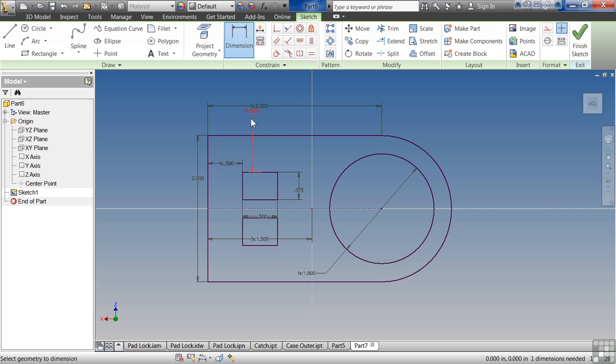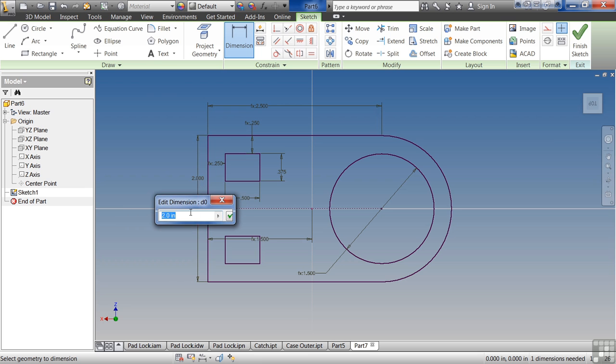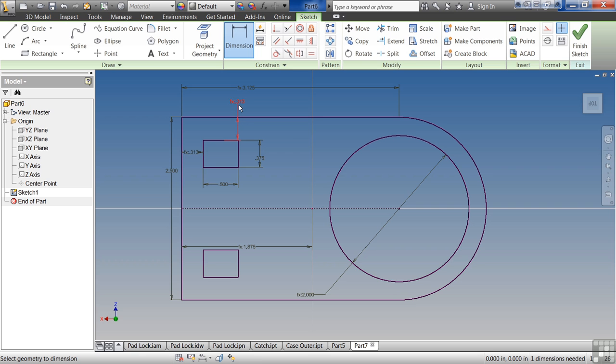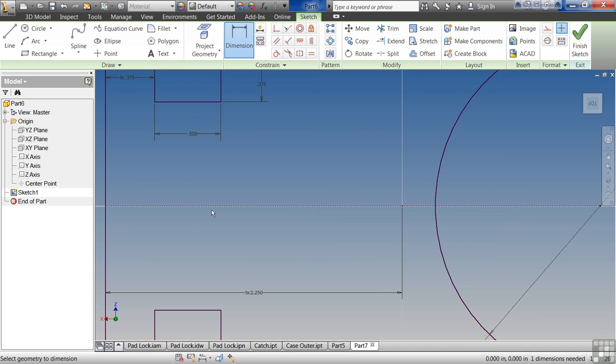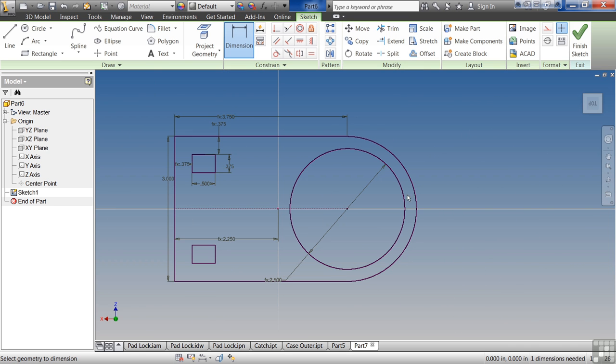Or make it a little bit smaller than that. Let's say divided by 8, which is a 1/4 inch. So now if I change this back to 2.5, instead of these being a 1/4 inch, they're 0.313. This goes out to 3. My circle, I wanted a 1/4 inch around it. These, I wanted 1/8 of this dimension. So they're intelligent. That intelligence is built into your sketch now.